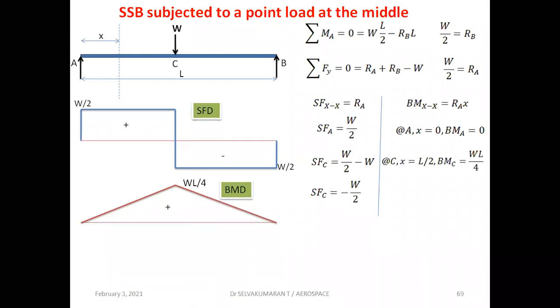So this is the shear force diagram and this is the bending moment diagram. Again, you can see here the shear force is 0, but the bending moment is maximum. Here the bending moment is 0, the shear force is maximum. That we need to understand.